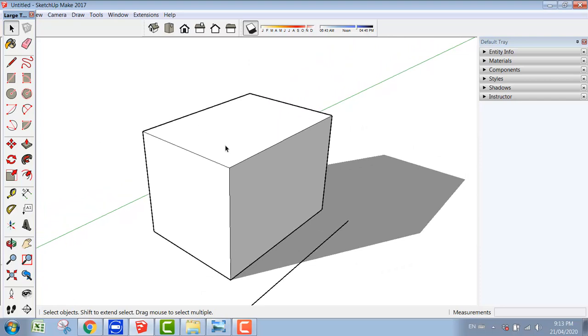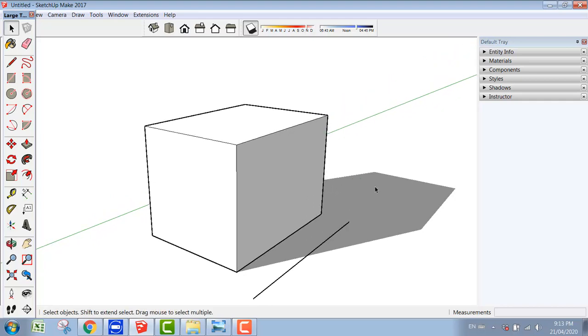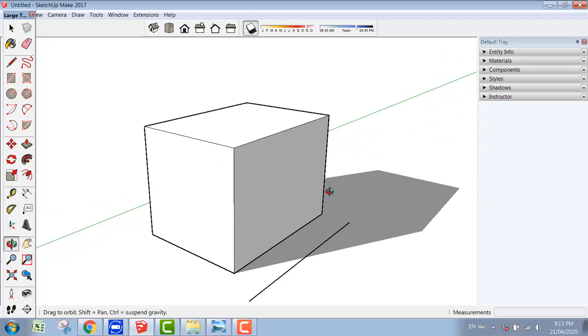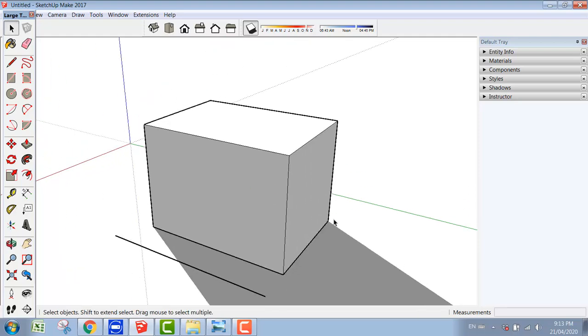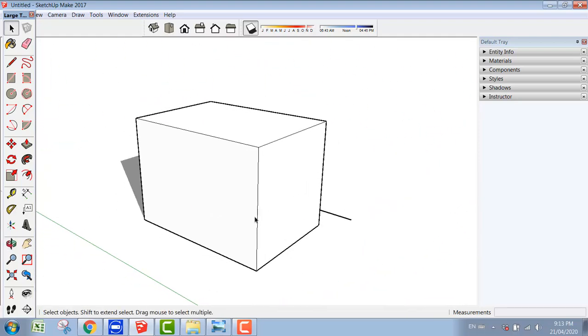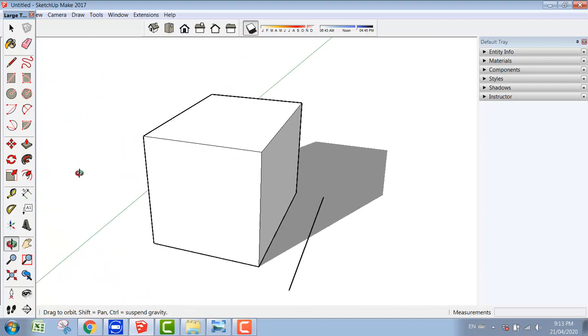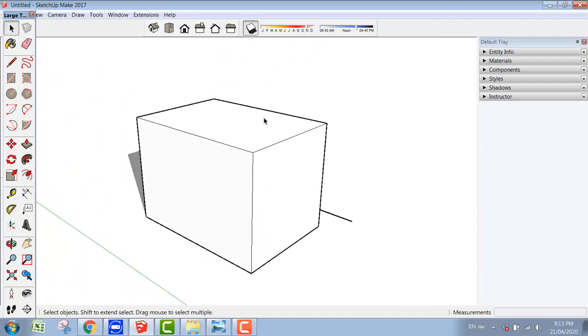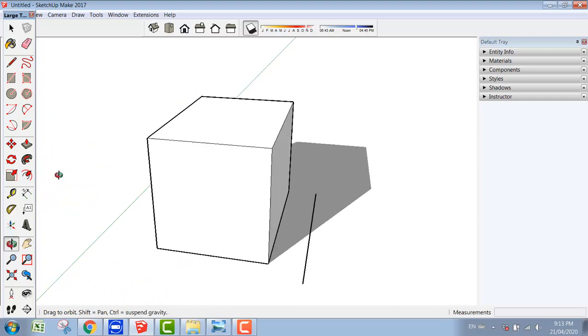Another useful feature is when we want to rotate the model, I mean orbit, so the model is fixed in its place, we only rotate our view. So how do we do this? By holding down the middle mouse button. So I come here, hold down the middle mouse button, then try to rotate it. Just do not forget, when you want to make this rotation, always bring the pointer through the area that you are working on, then hold down the middle mouse button, then rotate.